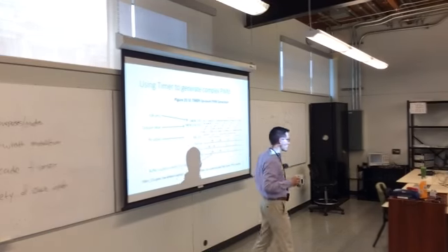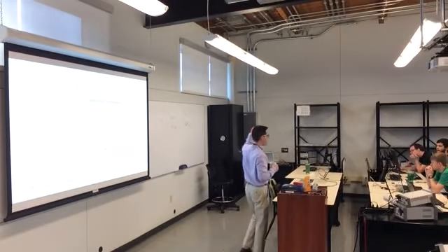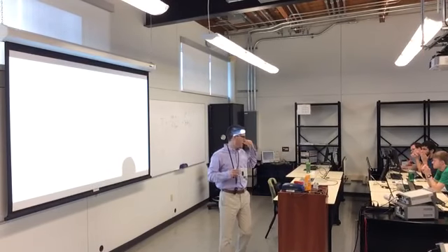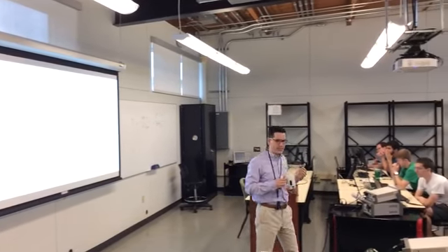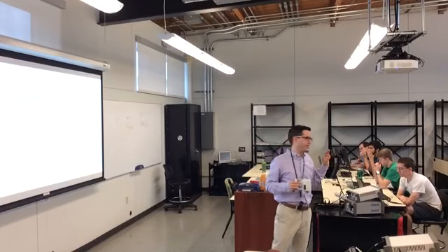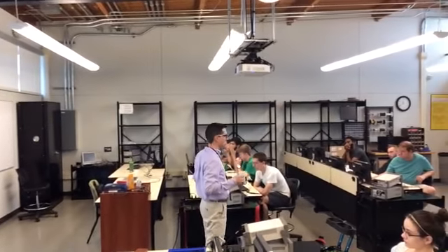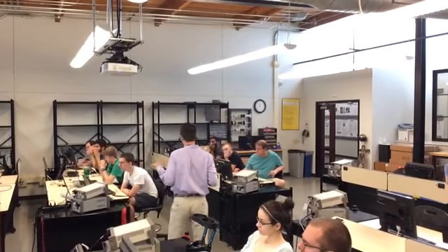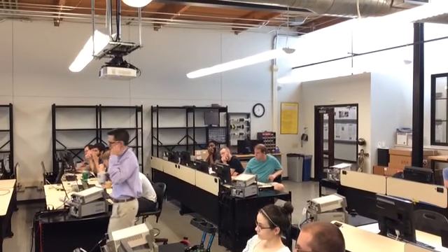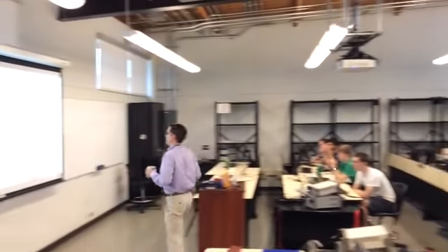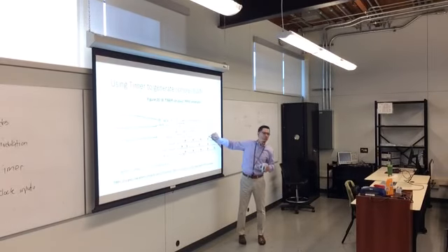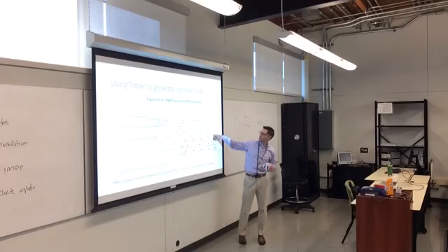By setting the CCV value, you're dictating when the pin goes low, and by setting the top value, you're dictating how long the wave is low. If you set the CCV value all the way down at 0, your pin is low the entire time.